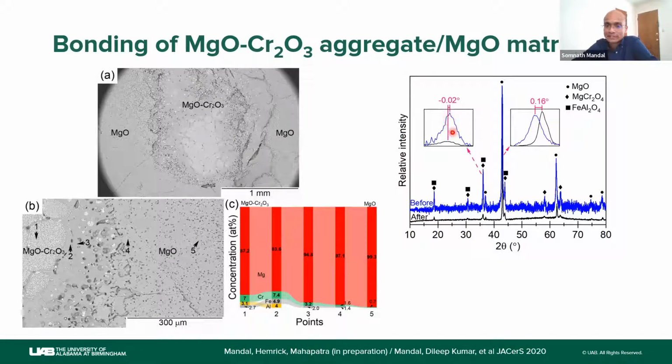But you see here that the spinel phase intensity after firing is almost gone, which means there is a lot of sublimation of MgCr2O4 (magchrome) as opposed to zinc aluminate, where we found there was minor sublimation. And this is a very big thing, because one of our reviewer comments in our recently published paper was about the sublimation rate. Does zinc aluminate have a higher or lower sublimation? And now we know that zinc aluminate is much better than magchrome in terms of sublimation.